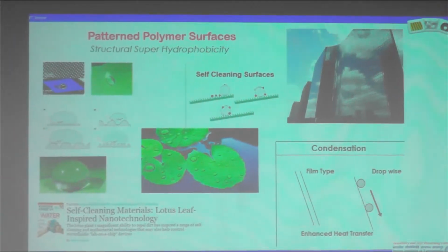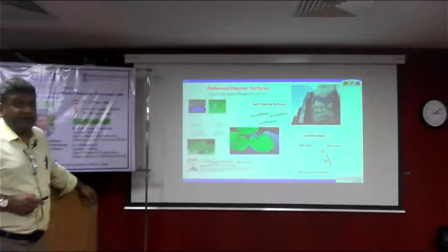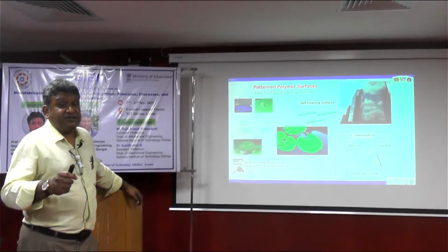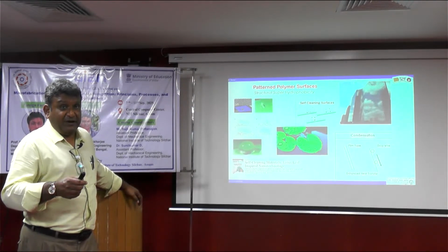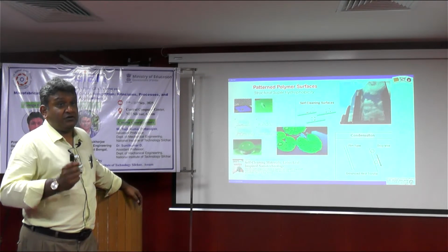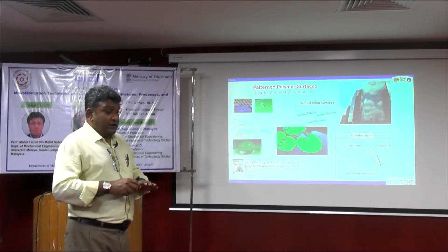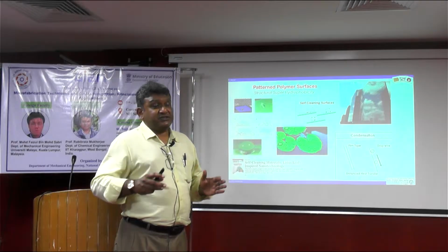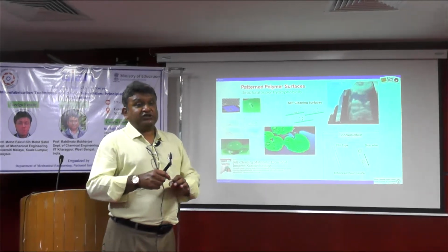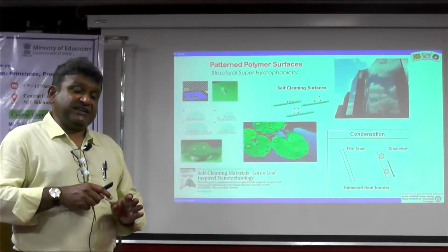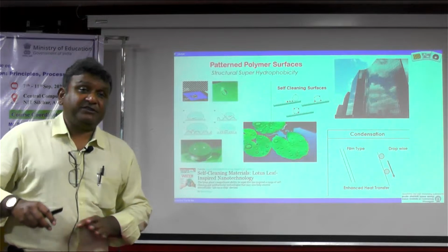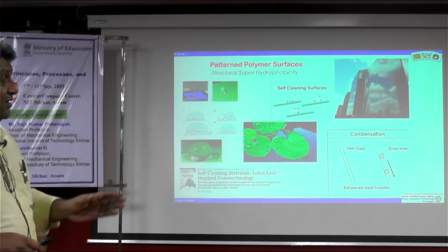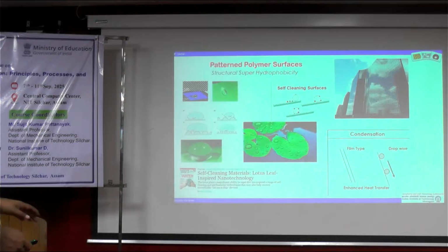Not to forget that corrosion is a major problem in metallic material, particularly iron. And one of the necessary conditions is crevices and cracks. Water gets entrapped, and because of oxidation, corrosion happens. So if you can cover these surfaces with some sort of coating or structures which prevent the accumulation of water, then corrosion, which causes colossal damage to GDP, and damages many buildings and structures in coastal areas, can all be hindered.